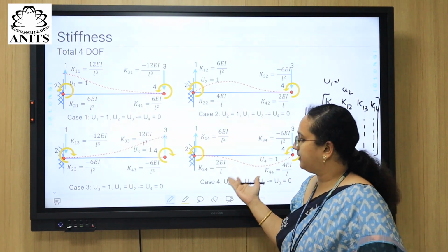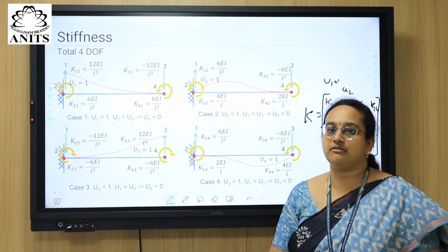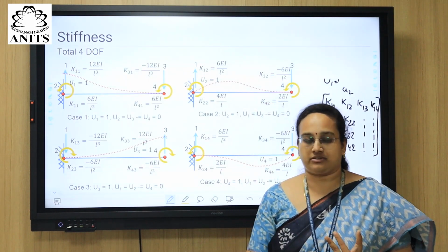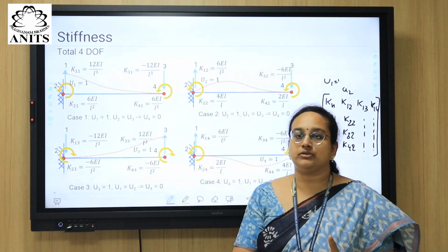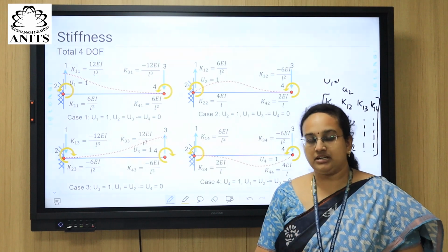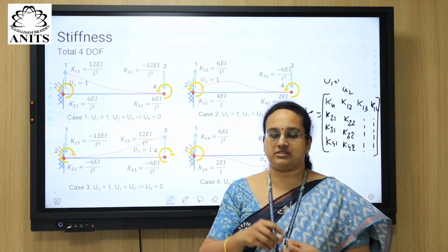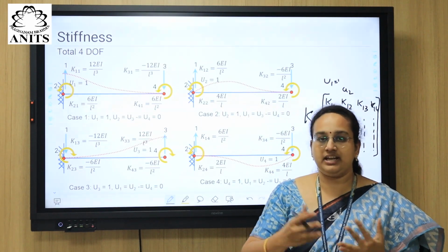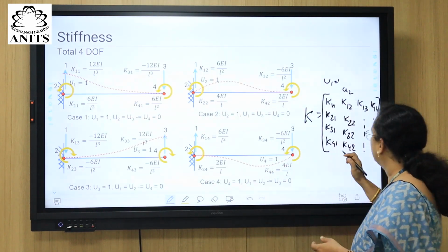But in the case of earthquakes or blast, which causes a dynamic force and lateral vibration, right? Dynamic force and lateral vibration when we are talking about structures. What we need to know is the stiffness in all the directions possible at a particular node, so that we can study the effect of force that is coming onto the structure in lateral direction or transverse direction, any direction for that matter, right? So that we have achieved.